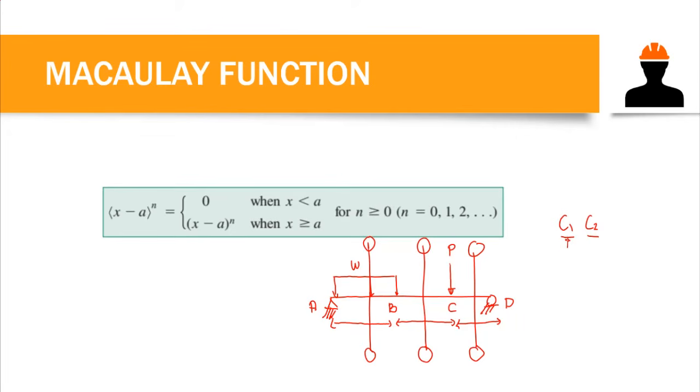So in this type of beam, instead of cutting it at every segment, we can convert this beam into a continuous beam. We just need to extend our load, so this width here must be extended up to D. However, since there is a new load introduced, we have to introduce a counteracting load with equal magnitude, like this one, so that it would remain the same.